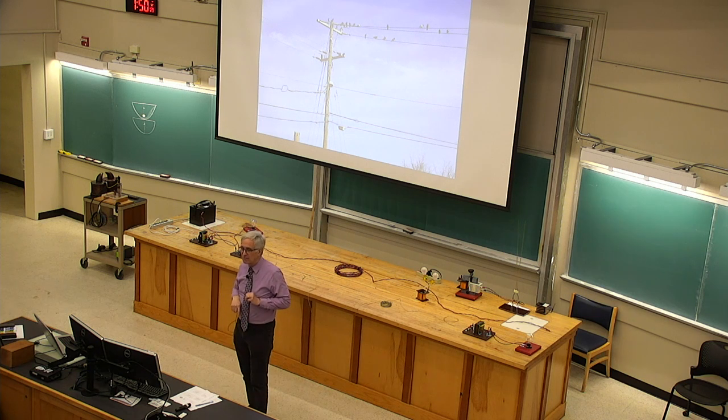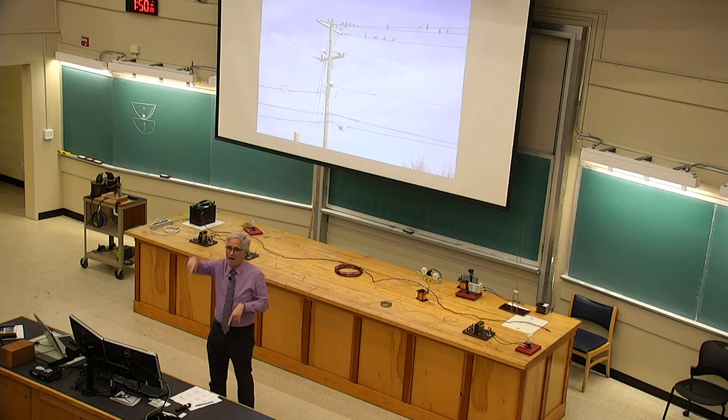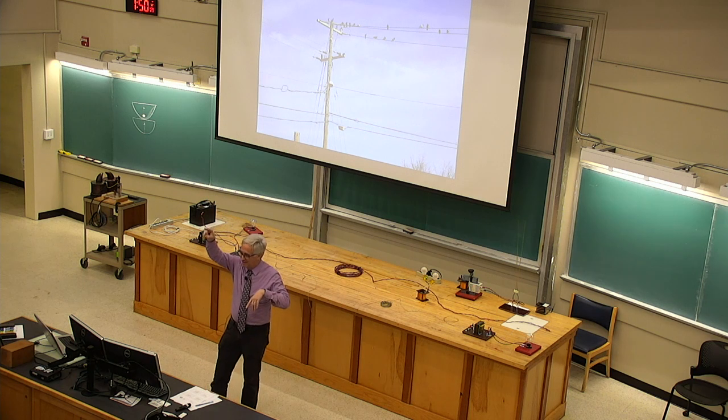120 volts AC should deliver the same power as 120 volts DC when it's delivering power to something like a light bulb or a toaster or a space heater or a hairdryer that don't care about the way electric power flows back and forth. So in order to get that average to work out right, the voltage of power has to rise above 120 volts because it spends a lot of time below 120 volts. So it goes above and comes back down. Then it goes below minus 120 volts, and then it comes back. And it goes up and down. If you plotted it, it would be a sine wave or a cosine wave, it doesn't matter. Up and down and up and down.